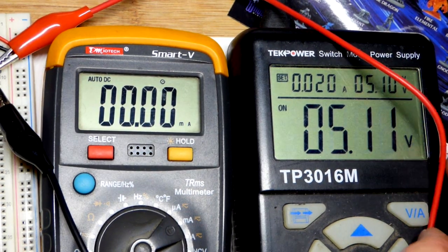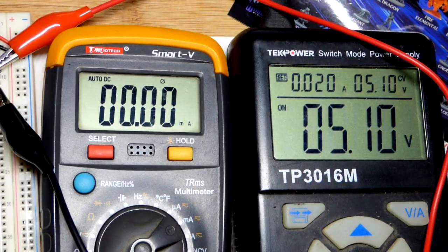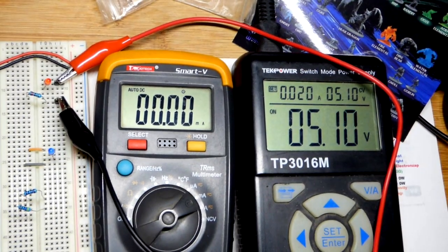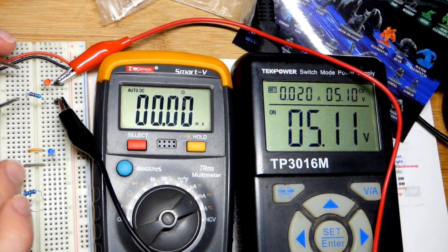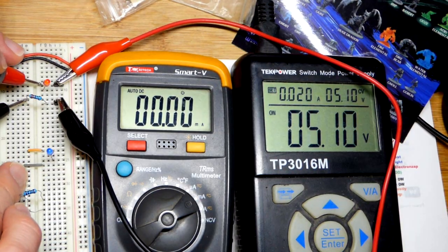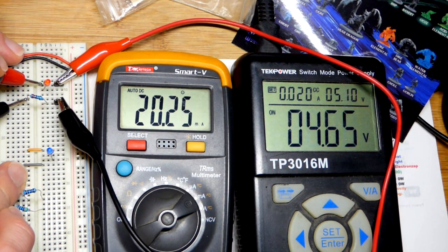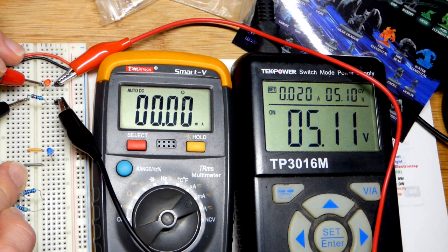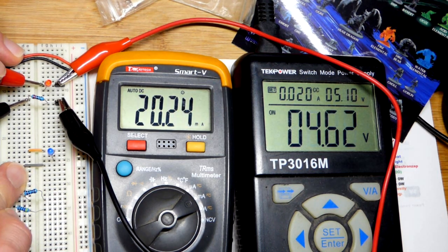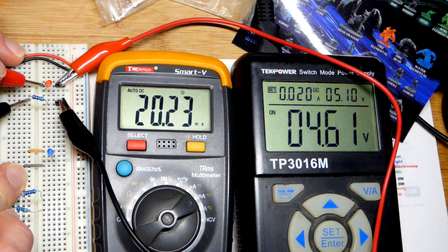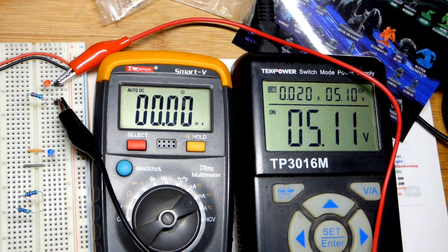There we go. I want to change this. Now it's showing the voltage, and what I'm going to do is try to just measure the current through the resistor alone right there. And you can see the power supply lowered the voltage. So it did that to limit the current. So 5 volts would have put more than 20 milliamps of current. I lost my connection through the resistor. So it had to lower the voltage in order to set 20 milliamps of current.